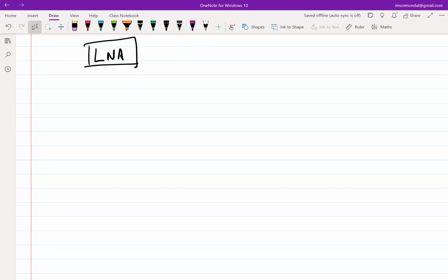Can you quickly tell me with regards to a design, what are the things that the LNA needs to be mindful of? Noise figure. Okay. So low, obviously, it is embedded in the name, like low noise amplifier. So low noise figure. What else? Linearity. Okay. Good linearity. Because ultimately, it is sitting just next to the antenna.